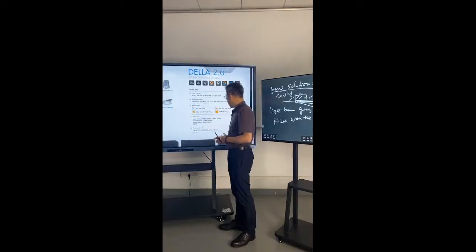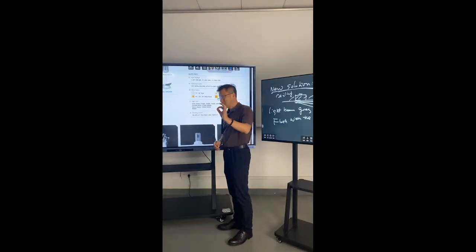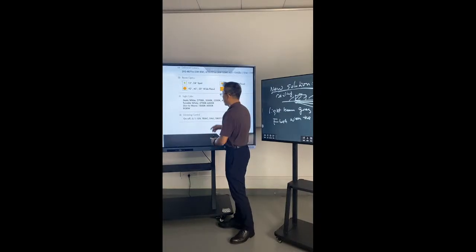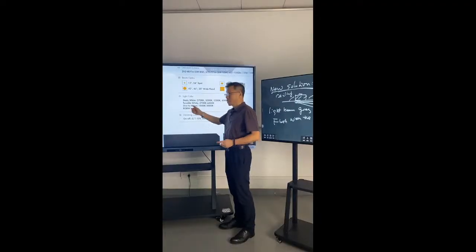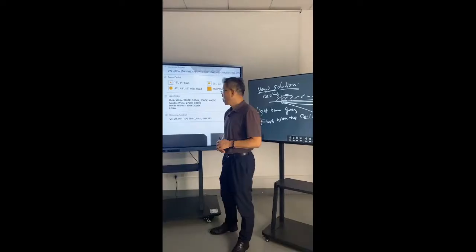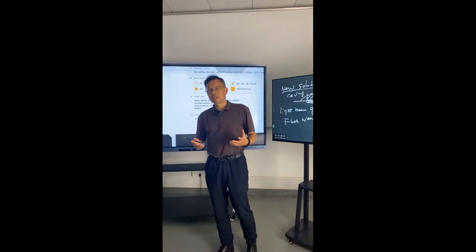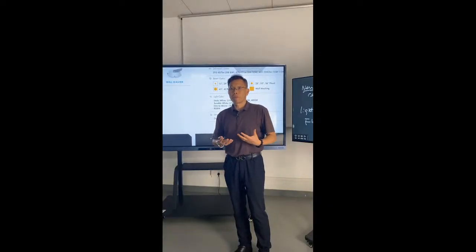And also we can do the wall washing, right? For the lighting color output, we have static white, tunable white, and also dim to warm and RGBW. Regarding the dimming method, we can provide on-off, 0 to 10 volt, triac, DALI, and DMX. For downlighting, any dimming method can be provided.